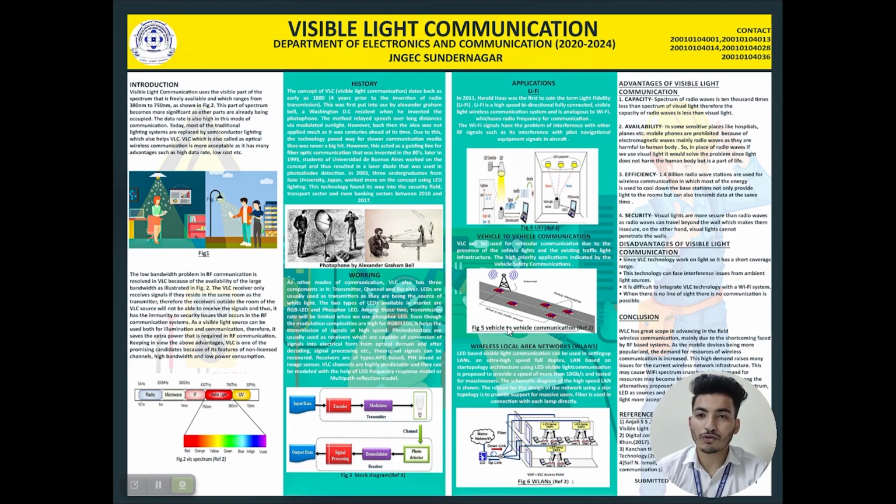Before the LED, we should connect the LED driver. An LED driver is a self-contained power supply which regulates the power required for the LED. It controls changing temperature and other factors. It is of two types, that is internal LED driver and external LED driver. After this driver, we should connect an LED, which is of type phosphor or a normal RGB light. Then this emitted light is passed to free space.